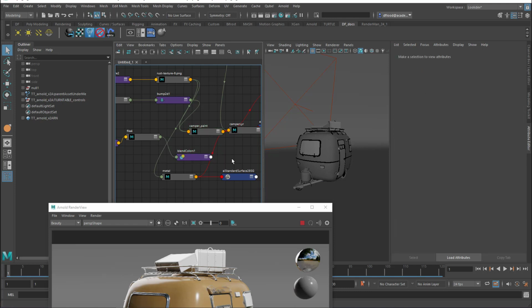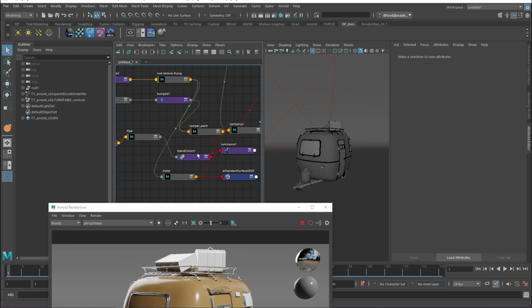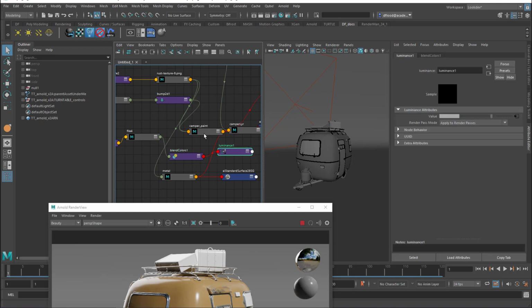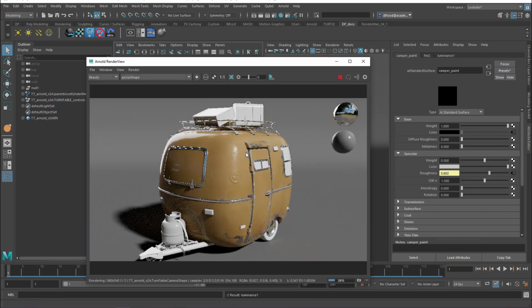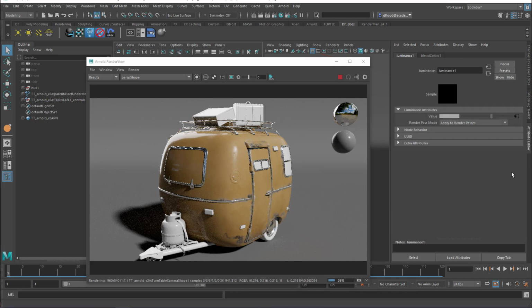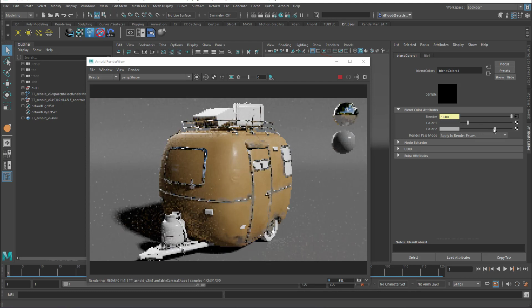And then I'm going to make a luminance node because I want to help Maya to figure out how to convert the triple channel for the blend colors into a single channel for the roughness. So I'm going to come into the roughness here, drag that into the roughness, and voila, you can see I'm already getting it in there. And I can then, just like in Substance Painter, move around these two sliders to adjust the values as desired, including flipping them around and doing the opposite with them if I want to.